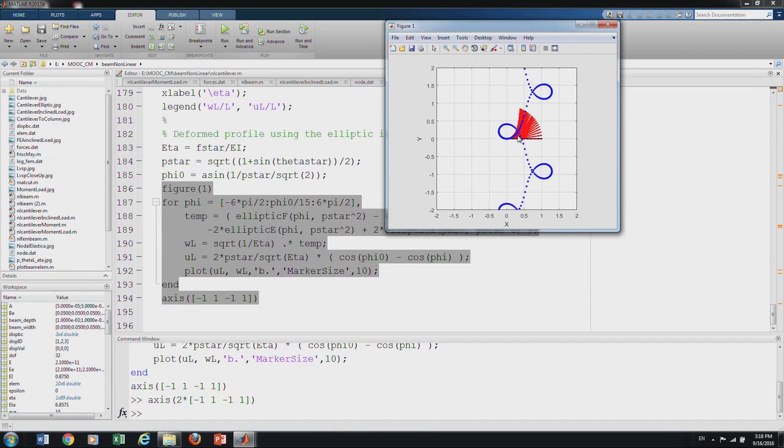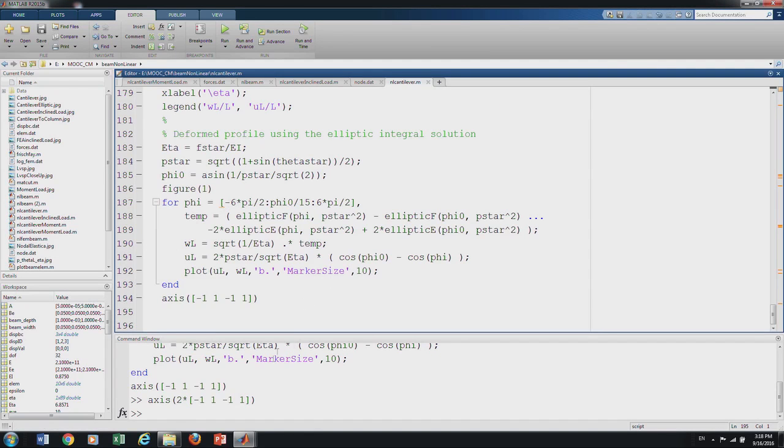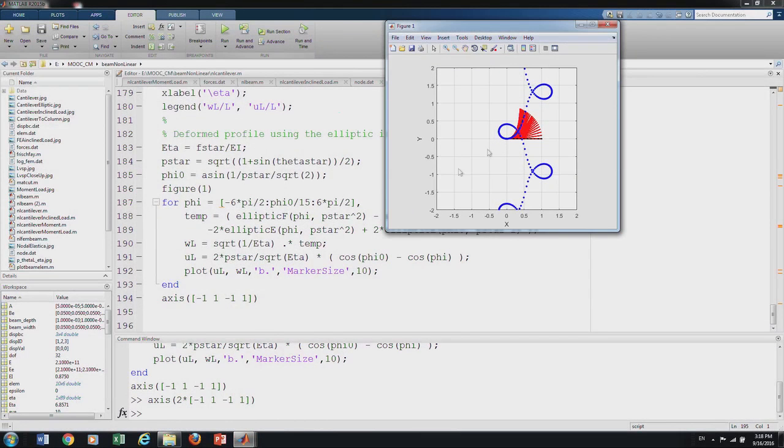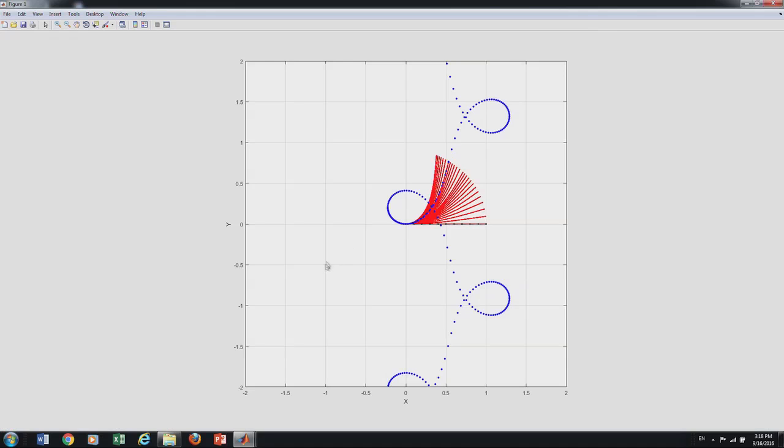Our cantilever beam is only this much. When I go up to phi equal to 0, it went like this. When I went to minus 3 pi, it bent like this, and similarly when I went up here, we have this. We see this nodal elastica that we had mentioned when we were discussing this elastica problem. We can play with this, and all the solutions that we see here depend only on one value, p, and the p changes from curve to curve. If I were to take this one, that nodal elastica, the p is different from that for this one, and so forth.